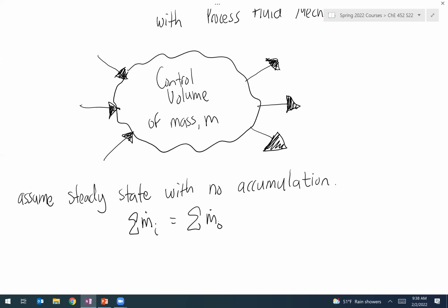Well, one idea is to produce excess steam of a certain percentage, let's say 10 to 15%, monitor the pressure, and when the pressure exceeds a certain value, you vent the excess steam. And so you essentially just produce excess amount of steam and vent a little bit of it to ensure that you have a little flexibility built into your plant. And what do you see in a lot of process facilities? Steam vents just kind of going off throughout the day, right?